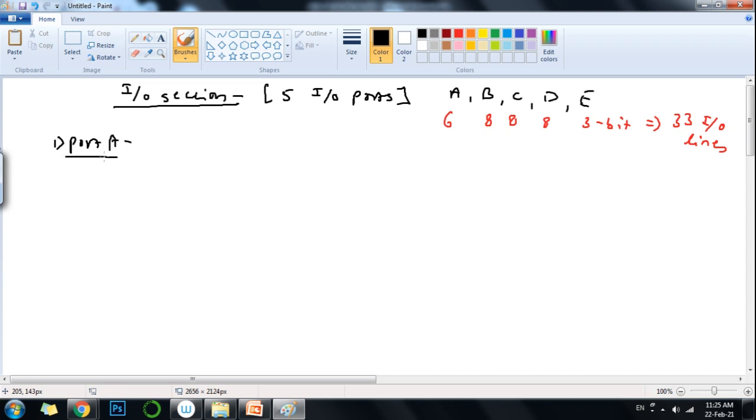Okay, so as we have seen, it is an 8-bit port. Port A can be configured as either an input port or an output port. So the I/O function of this port is decided by the TRIS A register. You have discussed this in the previous microcontroller also, same as that.